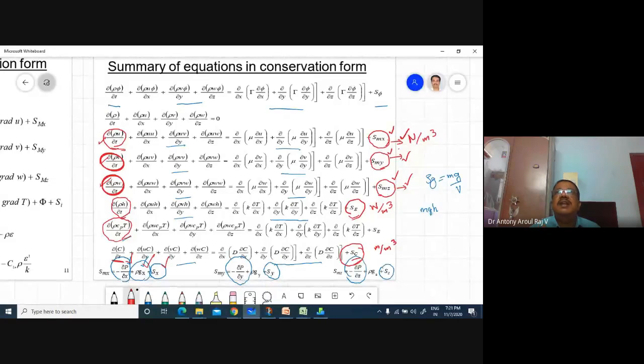What you see immediately is the velocity. So these are the convection terms we are seeing, the terms on the right hand side. What is the meaning of that? Whenever the source for the fluid flow is there, naturally it will end with convection. How is convection created? Just now I told you, because of velocity. When the source is there, it will create velocity, and because of that, convection of momentum will be there.